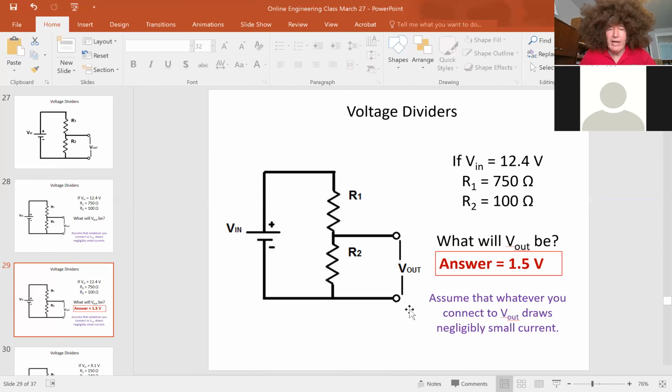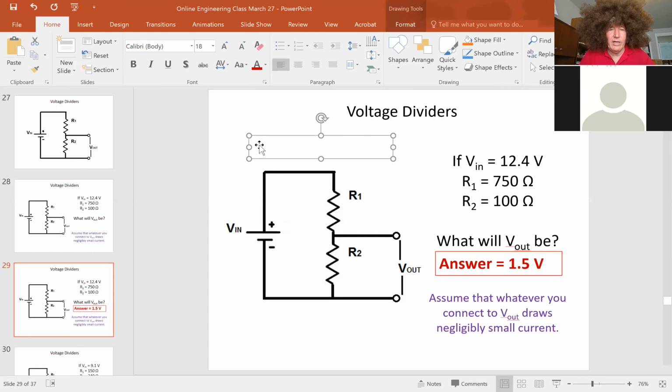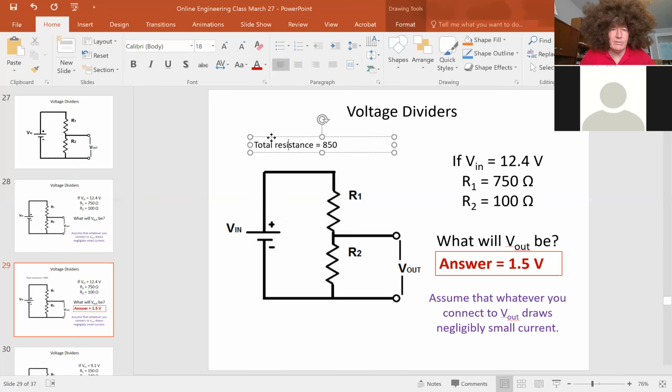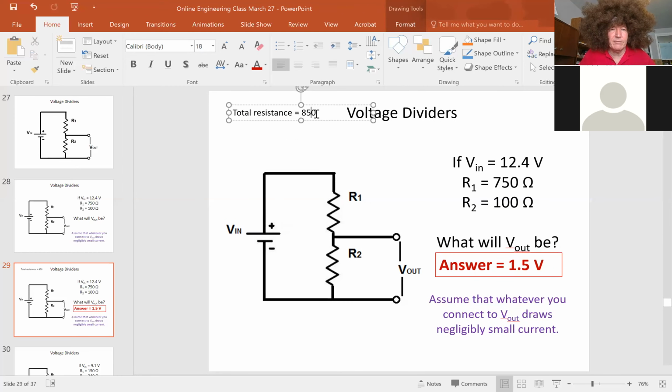All right, so the way that I recommend we do it is, first of all, actually, let me open up a text box here. Okay, so what I'm going to do here is I'm going to say, if it'll let me. Okay, you guys agree the total resistance is 850. I just add them all up. Okay, so what do I do next? Okay, so the next thing I do is I calculate the current.